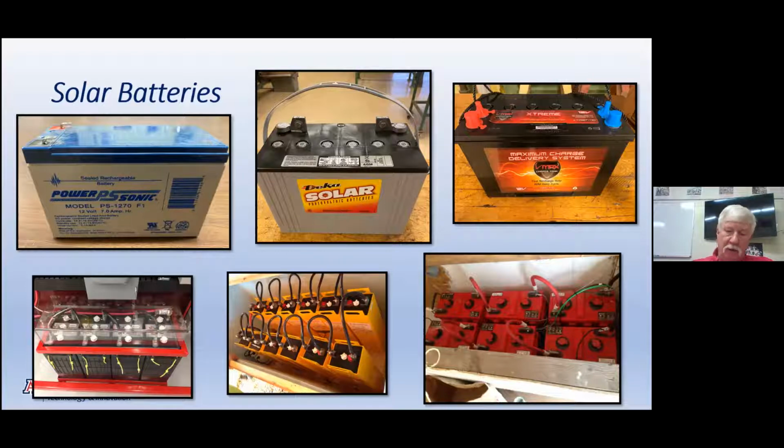So if you're looking at putting in a standalone system for yourself and you'd like to go with the lead acid option, be prepared. These are the ones where the owner has to go in and actually monitor and service the batteries. So you're going to be checking to see how much distilled water you have and having to actually monitor the batteries.